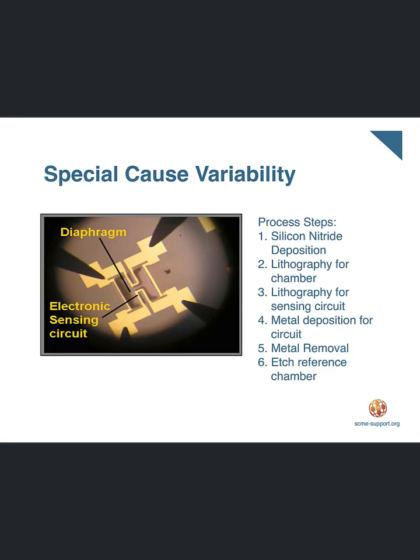When considering a manufacturing process, variation can become even more prevalent. Each manufacturing process contains one or more process steps. For example, a micropressure sensor's process may include depositing a layer of silicon nitride for the membrane or diaphragm on a bare silicon wafer, followed by a photolithography step and an etch step that patterns the reference chamber hole on the backside of the wafer.